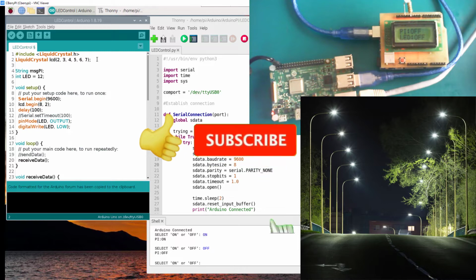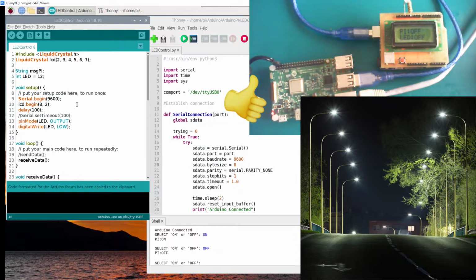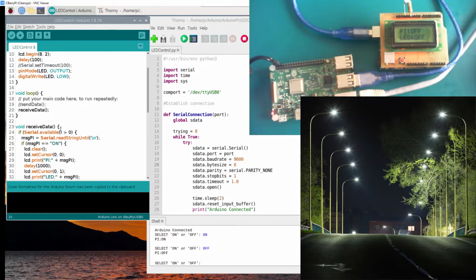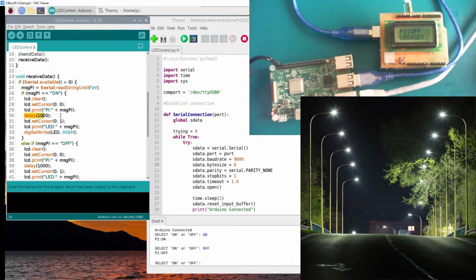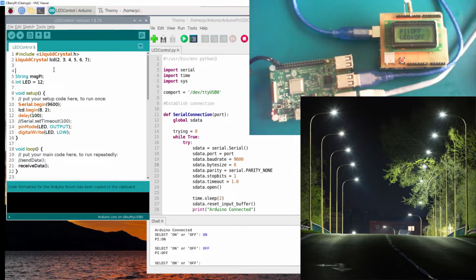So the first thing I'm going to do is to create two variables. The variables that I'm going to create will manipulate the delay system. Here we were just calling the delay function and pausing everything for 1 second. This is wasteful. It's wasting the CPU just to sit there for 1 second. So I'm going to use a state machine so that we can pause without delaying anything.